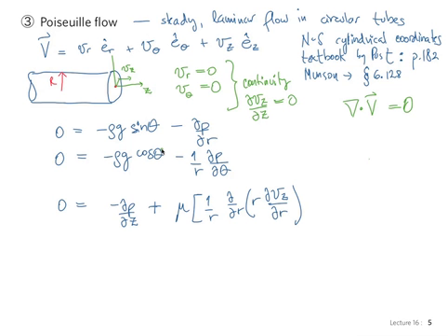We're applying the chain rule to the velocity, and because the velocity depends on both space and time, you get all these partials, remember? And the partial of the velocity with respect to time is the unsteady term. If that term is zero, we call the flow steady. But a particle itself could still feel its velocity changing when it moves from point A to point B.